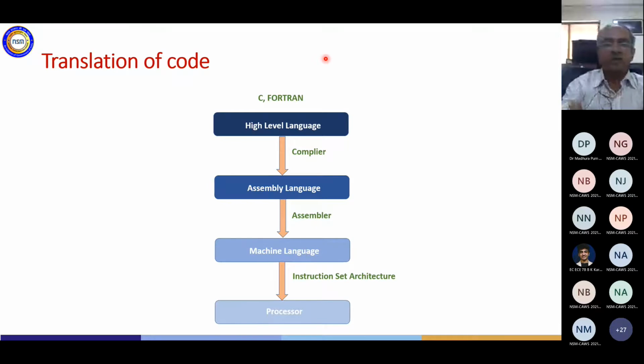Let's say you take 8085 or any other microcontroller. It will have a data sheet in which all the instructions that particular processor can execute are listed. So an instruction set is a set of instructions, but when you add the word architecture, it also includes a few more things like how many registers there are, what the addressing modes are, and where the operand can come from. All these details about how the processor is going to execute those instructions are indicated through this instruction set architecture.